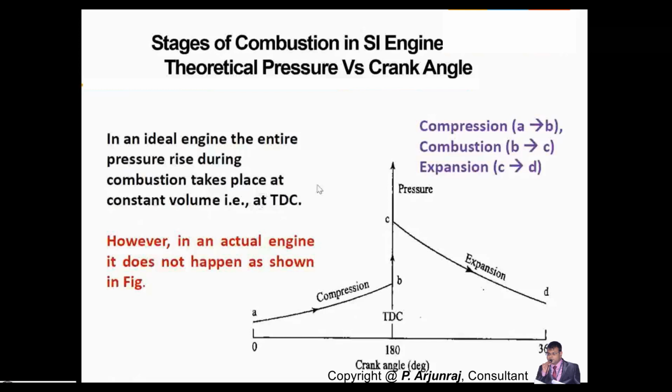When the piston moves from TDC to BDC, that is the first stage, the intake stroke. The next one is the compression stroke, when the piston moves from BDC to TDC and the compression happens. That is the compression stage. At the end of compression, the ignition is not going to start; you actually get the ignition before the end of compression, which means before top dead center.